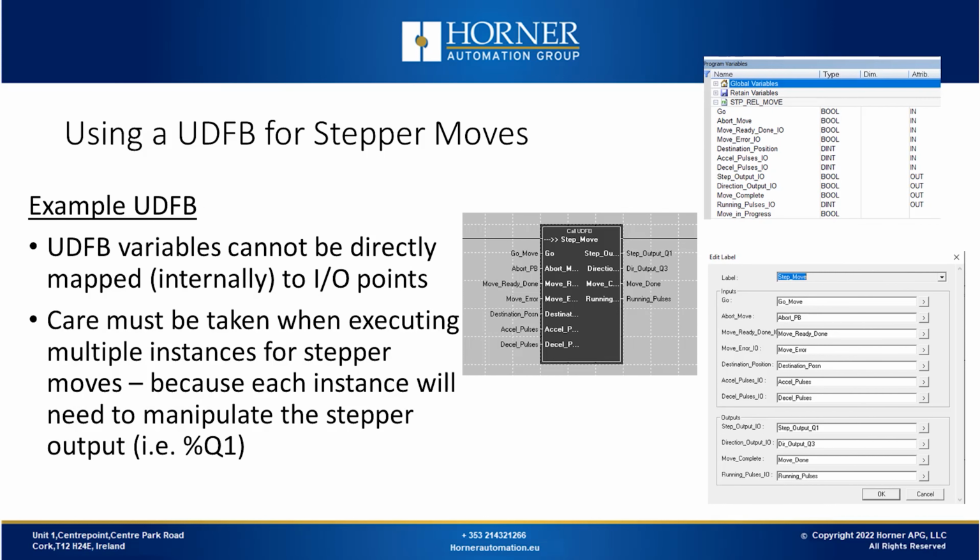Keep in mind that UDFB variables that you create cannot be mapped to I/O points. The variables that are connected to them can be, but the internal variables for the UDFB cannot. Also keep in mind that you have to be careful with UDFBs if you have multiple instances manipulating the same output bit.